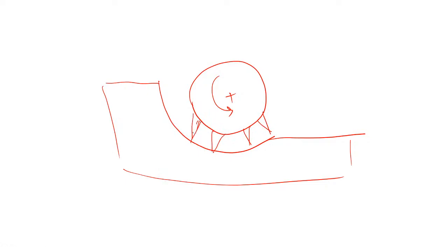Machining occurs because of electrochemical dissolution, just like in the normal ECM process. The circular grinding wheel is the negative terminal, the cathode, and the workpiece is the positive terminal, the anode. The grinding wheel can be made of graphite, which is a very soft material, mixed with abrasive particles. So there will be electrochemical dissolution between this cathode and anode.